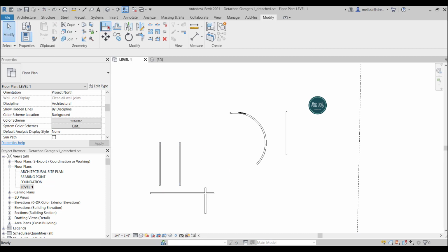The other option is your preference on what you're aligning to. And by default, it's wall faces. I always leave it as wall faces because generally I find that you are aligning to wall faces. Like you may be aligning some cabinetry to a line face or something. Very rarely are you aligning something to the wall center. So to recap the Align tool, you're clicking on what you want something to align to is your first click. And your second click is the element you want to move over to that spot. And that's how that works.